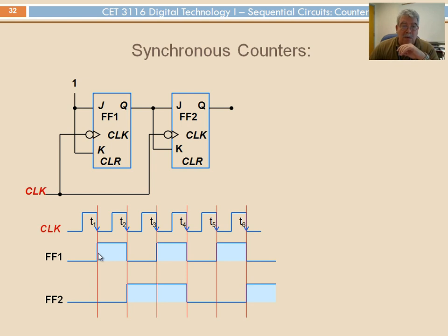There's a transition, and there's a bit of delay, so we are not reading a 1. We assume that this 0 to 1 transition happens after the clock goes from 1 to 0. Therefore, at this point, what we're reading is a 0.